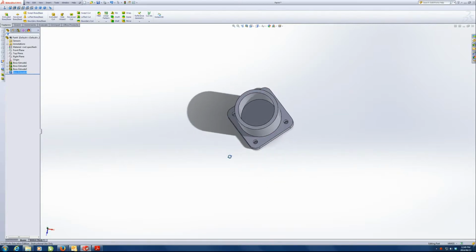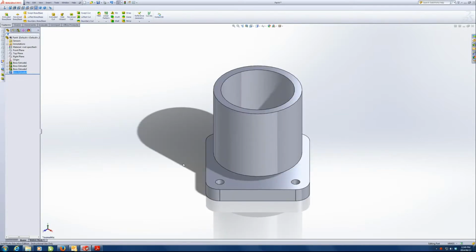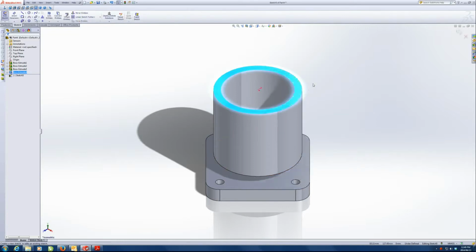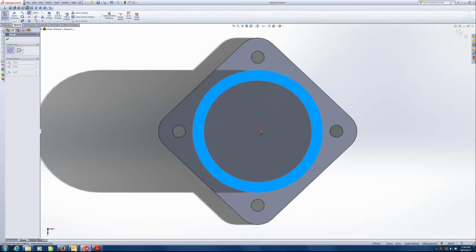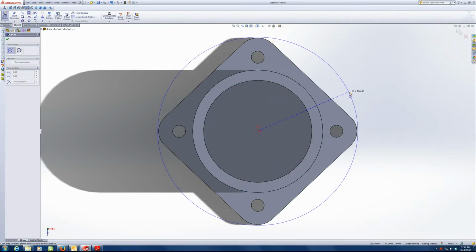Now the next step that we're going to take is, let me just see, draw that lid on top of this. Let's draw that sketch, normal 2. Big diameter, and it has a little hole in the middle. Let's have a look at the size of that.